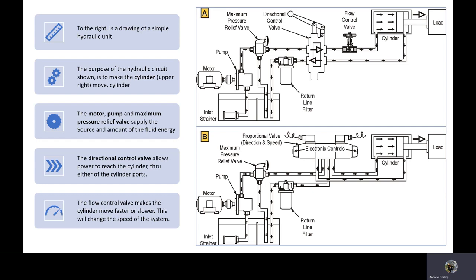The second, of course, is to provide an area for the fluid to cool down. As the fluid is driven through pumps and through actuators and through spool valves, control valves, and what have you, it builds up heat. Excess energy that isn't used by the hydraulic system to drive a cylinder or to rotate a motor is given off as heat. So heat is the waste product of a hydraulic system.